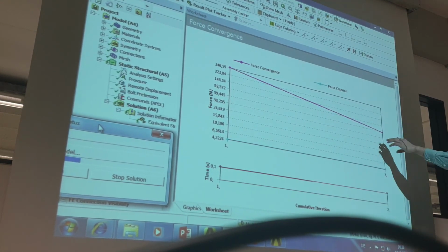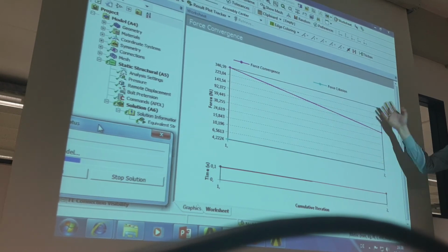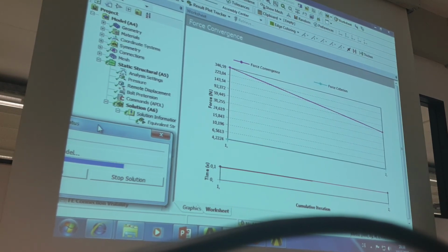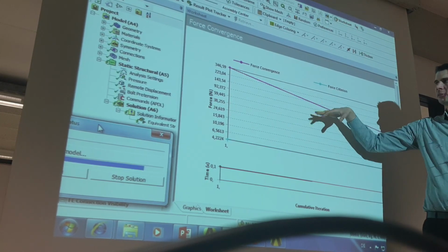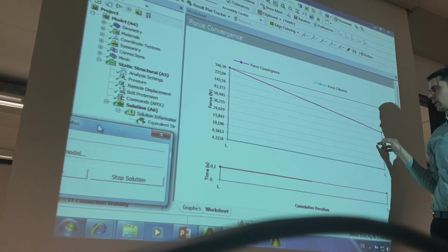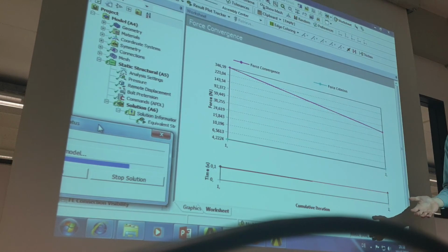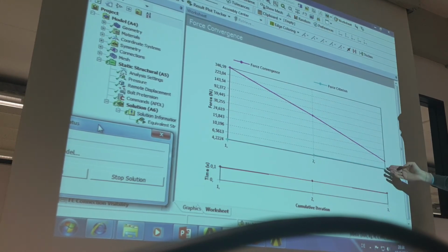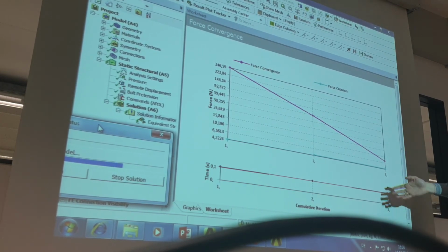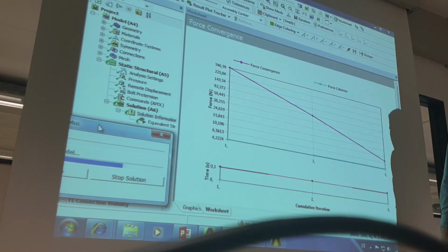Sometimes you can see that, for example, the second iteration needs maybe 5 minutes. So it works, for example, with one iteration every half minute, and then you have a pause of 5 minutes. It means that the program tries to do this iterative process and cannot find a solution. You're waiting, and maybe the program tells you no solution.